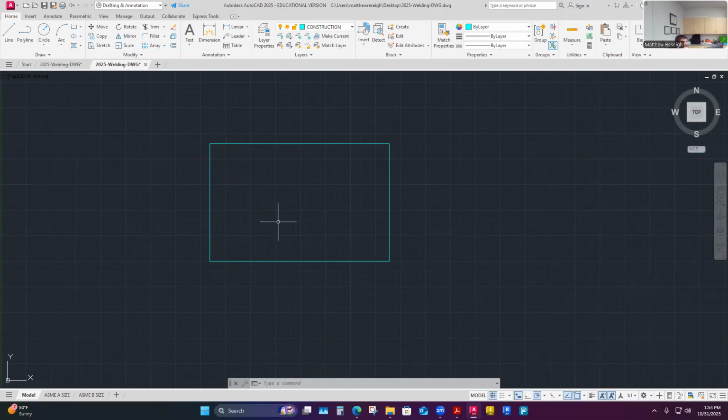especially if it's a machine cut drawing. But in all of our drawings, that's why O snaps are the only way we can draw accurately. Otherwise, we have to zoom way in and we'd never get things linked up correctly. So usually geometry has to hook to grips or snaps that are associated with it in order for it to be drawn correctly.